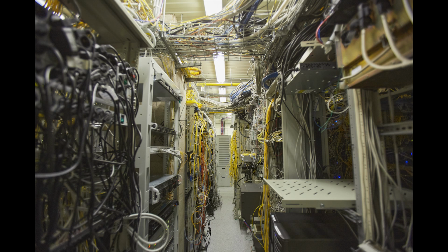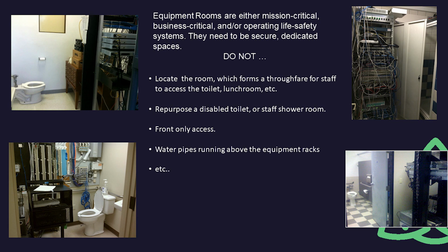The door must be of solid timber construction. It must be a 45 mm thick, flush panel, block timber, solid core door that meets the minimum fire rating requirement. Doors outside an office environment must be fitted with adjustable weather and dust seals to prevent ingress of dirt, dust, water, contaminants, and insects into the room.